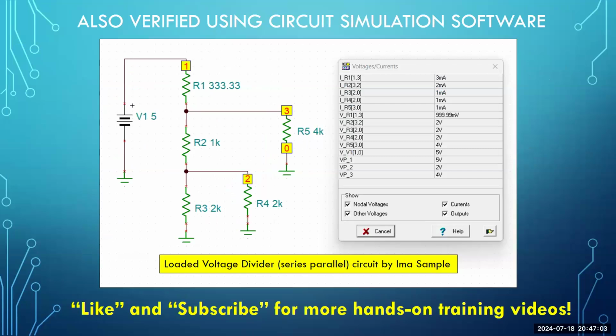R1, which is 333.33 ohms. We have a new value of R2, which is 1k ohms. R3 remained the same at 2k ohms. R4 was designed to have 2 volts with 1 milliamp flowing through it, so R4 we determined should be 2k ohms. R5 required 4 volts with 1 milliamp flowing through it, so we determined R5 should be 4k ohms.